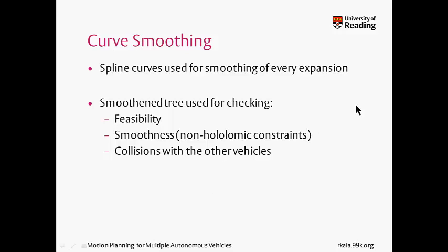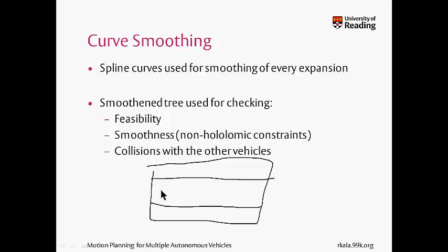The other very unfortunate problem with the use of RRT is that they generate very funny paths. So in a very simple road-like scenario, they'll generate paths like this. And the spikes, of course, cannot be traversed. If it's an actual spike, no matter how strongly you steer, you'll never be able to follow it. Vehicles can only take smooth steering, or they can only traverse smooth paths. So an element of smoothness has to be introduced, so that the actual trajectory can be traversed by the vehicle.